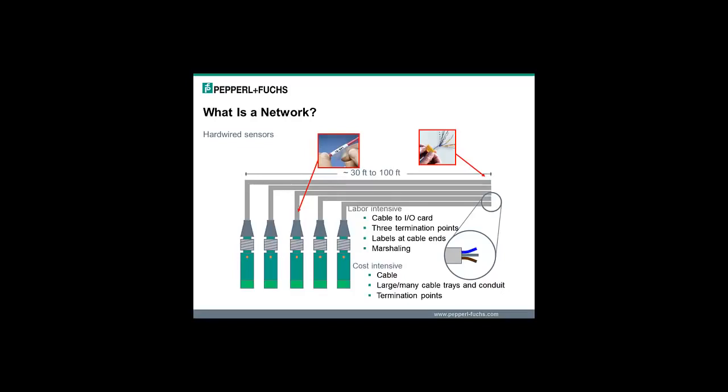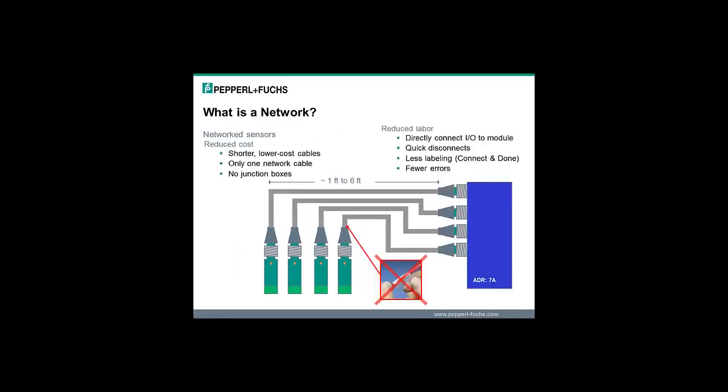Networks in general, and AS Interface in particular, address those problems very well. The main difference between a hardwired approach and a solution utilizing a network is that the I/O is brought closer to the sensors. The PLC backplane does not need costly I/O cards any longer, but instead provides means to communicate with the I/O modules mounted in the field, close to the sensors.